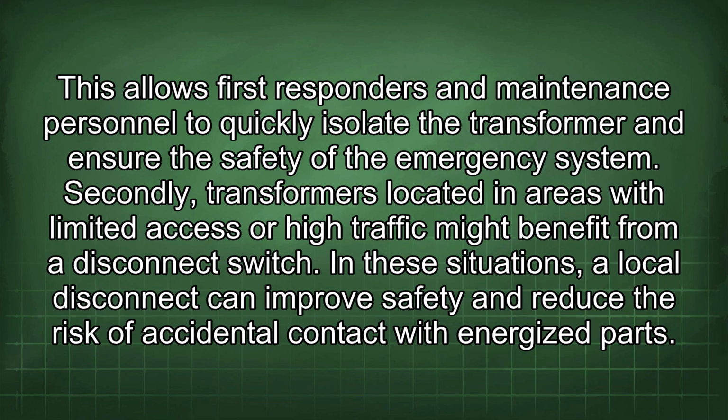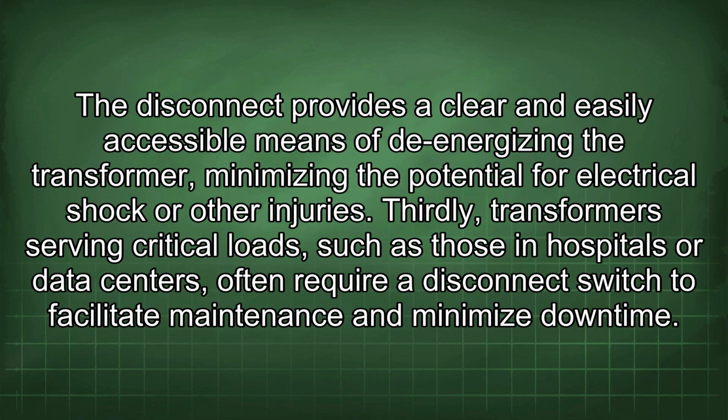Secondly, transformers located in areas with limited access or high traffic might benefit from a disconnect switch. In these situations, a local disconnect can improve safety and reduce the risk of accidental contact with energized parts. The disconnect provides a clear and easily accessible means of de-energizing the transformer, minimizing the potential for electrical shock or other injuries.